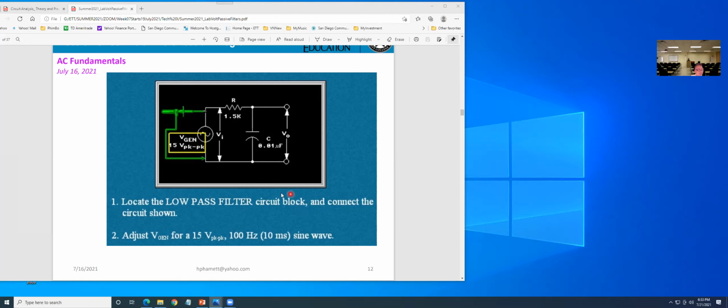Okay? So now, if you check that by connecting channel 2 right here, you get exactly the same signal like channel 1. So you don't have any problem with scope channel 2. Now you connect back into here, and they still don't get the right answer. What can you do? Call the instructor, because there's something wrong with this circuit.